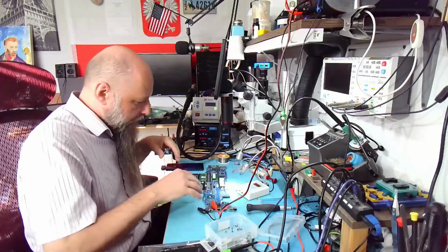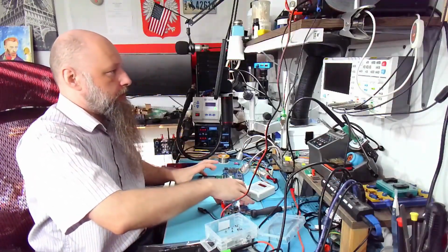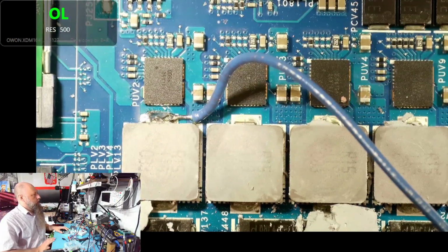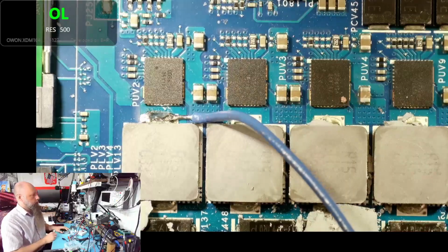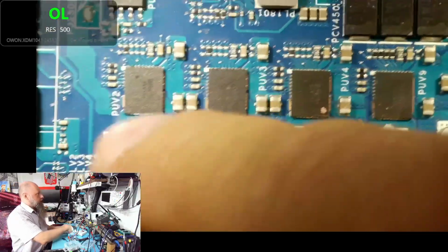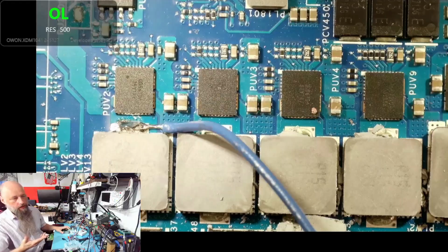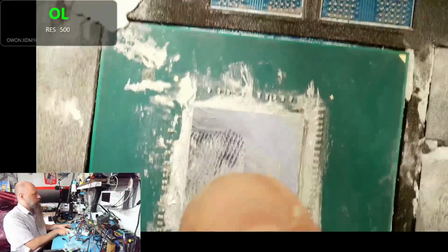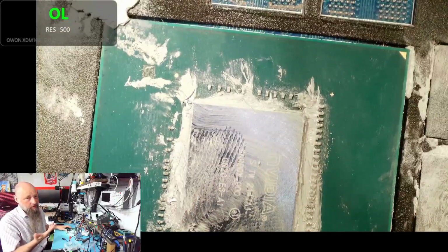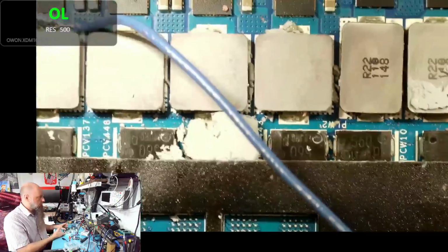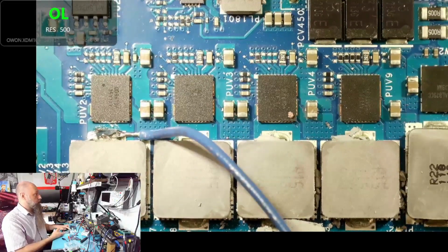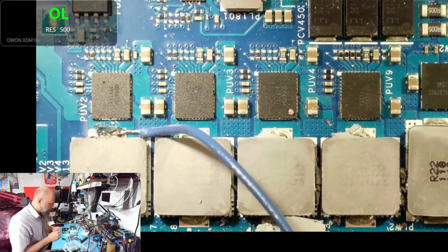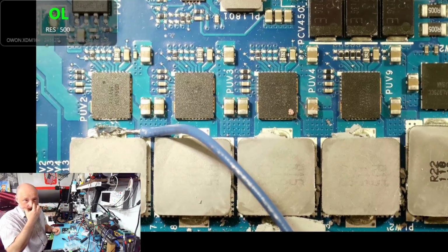All right, the board is out. We have soldered a wire to one of the coils, right? So now the question is, what is going to light up? If one of these lights up, we're good. We're just going to replace it and it should work. But if instead the core lights up, which either case it will be because we're injecting voltage to the rail over here, right?